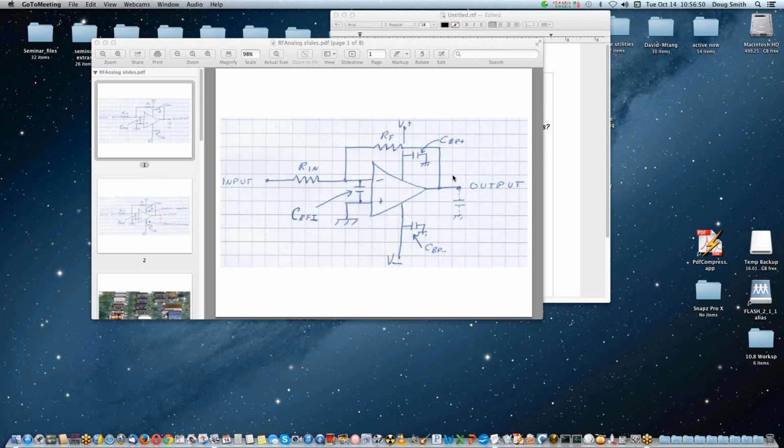Sometimes, if you're worried about a specific excitation like a cell phone, you could build a small coaxial dipole, and if I get an email, I'll send a link to how to get that. You could excite it from a signal generator to simulate a cell phone and hold it near your circuit layout to see the effect of someone holding a cell phone on top of your product.